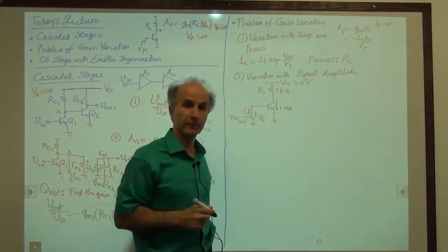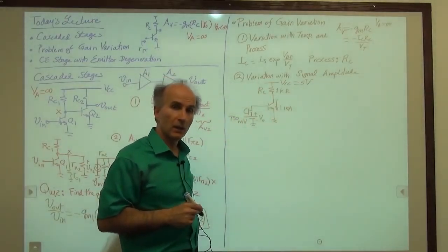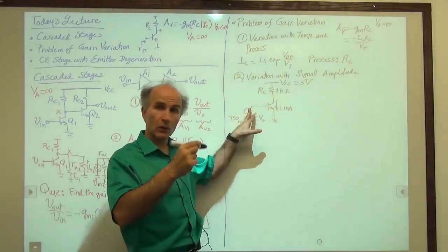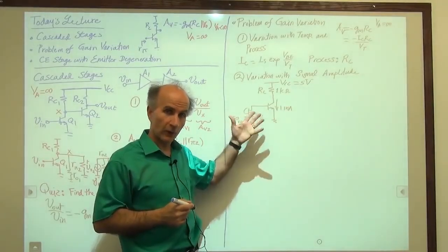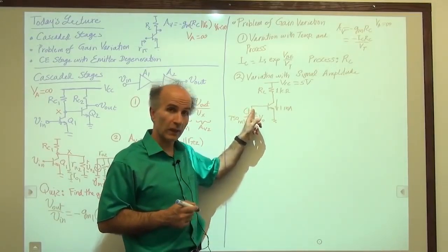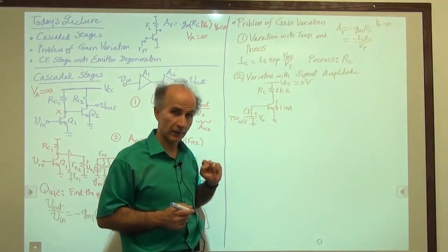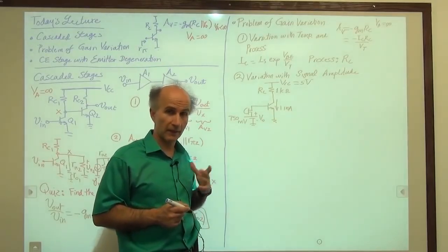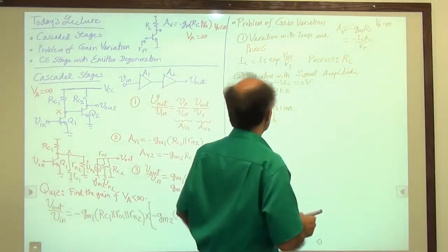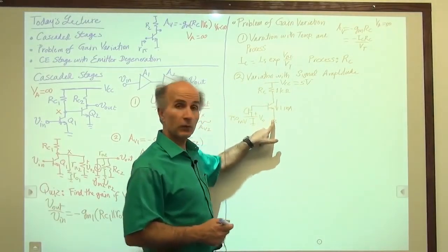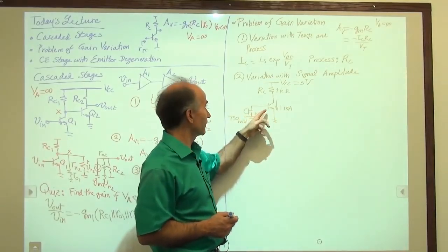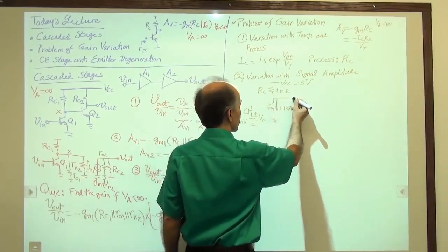Just as an example. And now we would like to see what happens when this microphone produces a small signal or a larger signal. So far we have always assumed small signal analysis, meaning that this signal creates only small changes in this current. But that need not be the case, and all sorts of interesting things happen. Okay, well, let's try to plot the base emitter voltage as a function of time while the microphone signal is coming in, and also the output voltage as a function of time.